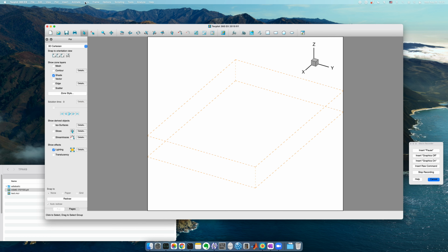I first need to define the zone on which the three-dimensional data is interpolated before it's actually written. So I want to create zone, which is rectangular. Here I'm extracting only along the x-axis. By the way, a capital I indicates the index for the x-axis. Maybe I can have 1,000 points. And along the second and third directions, which are y and z, I only want 1 point.